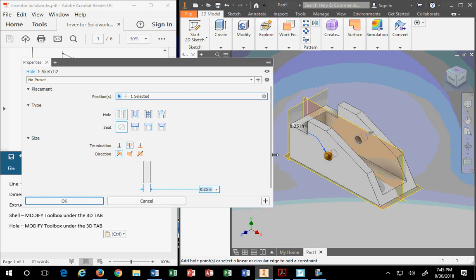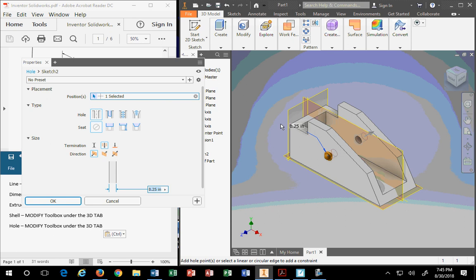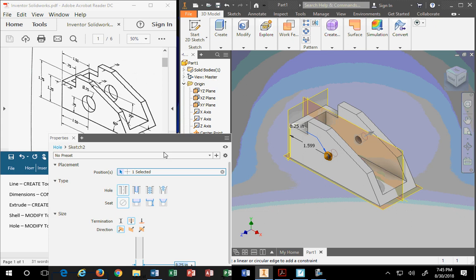We don't know where it went, do we? We do not have the dimensions. So notice what you do. If you take your mouse and drag it to the side, you're going to see a little icon up here of a line with a little dimension arrow above it. When you click on this, it wants to drop the dimension. So I drag this right over my part.